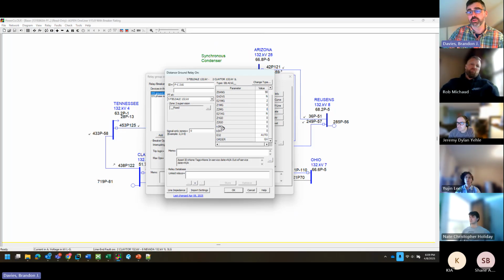When you do, you will be able to then see your protection on the RX diagram and see how it responds to various faults. The phase will be set up very similar to this. Won't have the zero sequence compensation factors. It won't care about zero sequence magnitude, so you won't have to put that in there. But that's largely what you'll use to model these faults.